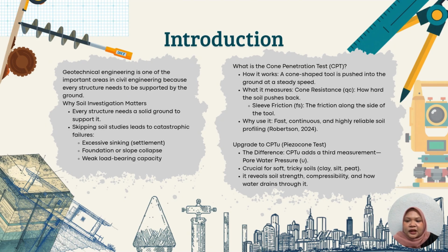Other than that, we can upgrade the CPT into the CPTU, which measures a third parameter, which is pore water pressure. It is crucial for soft and tricky soils such as clay, silt, and peat, and it also reveals soil strength, compressibility, and how water drains through it.